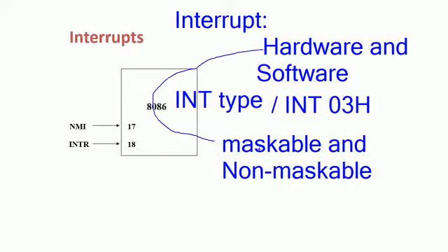So that is called a non-maskable interrupt. Here we are having two types of interrupts now. One is maskable. Don't get confused: maskable means I'm not going to attend that one immediately, I'm going to attend it when I'm free. But non-maskable means I should attend that one whether I'm free or not, irrespective of my present status. I have to attend that particular request. That kind of request is called a non-maskable one.